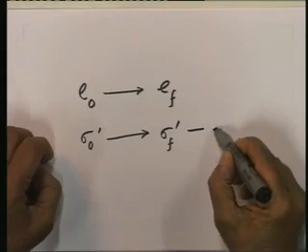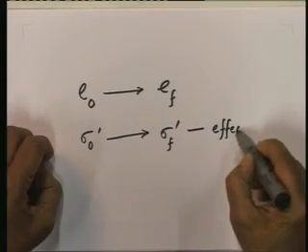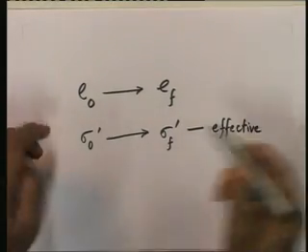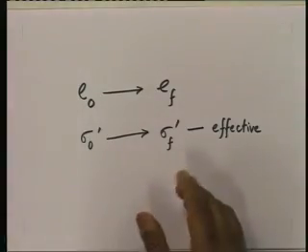Why are we considering effective stress? As we discussed in the last lecture, the explanation is that it is the effective stress which is transmitted ultimately to the grains of the soil solids, and that is what is responsible for the actual compression, or the change in volume that takes place.